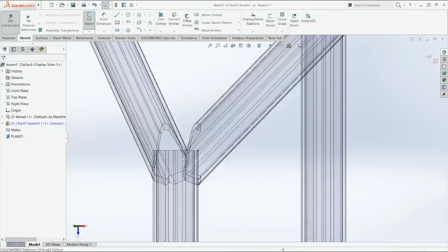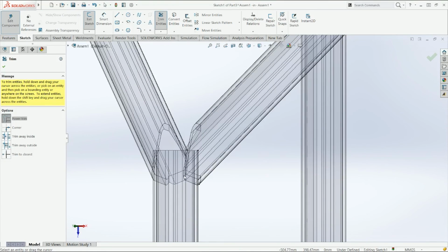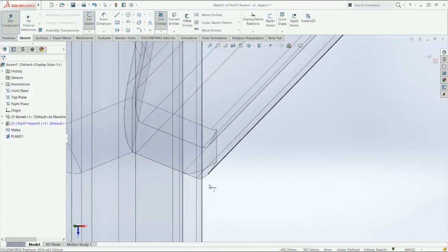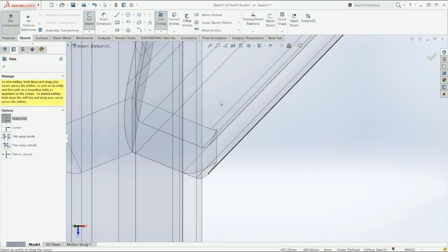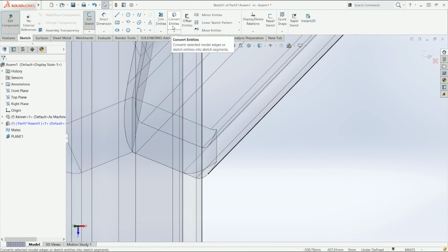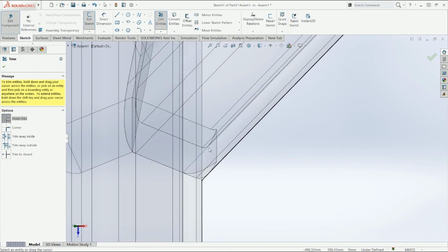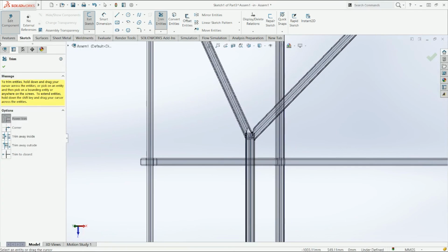And I also want to trim this one. Oh, extend first. You see the gap there? That's what's telling you that if I trim this, it's going to get deleted, because there's no other segments that can be used as a reference, as a finish point. So now that I extend it first, it's got that reference and it will have it like that.